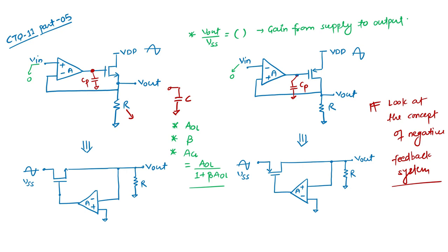So these are the ways you can analyze your circuits in various ways. This amplifier is not an ideal block. It is designed by some 5 transistor OTA blocks, or maybe some two-stage op amps, maybe the folded cascode or telescopic structure. So depending on this, you can consider whatever you want to put inside this amplifier block, that is A.